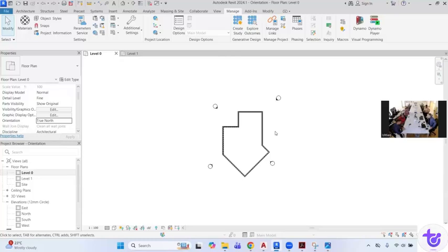Okay, I have one question. Yeah, sure. Not about this one. What is the use of the IFC format? IFC format is basically used when we want to have the Revit geometry used in a different workflow. So that is a bridge to build the compatibility between two different workflows. For example, if I want to use a different geometry, maybe from Rhino or Grasshopper, for integrating different software. Exactly.